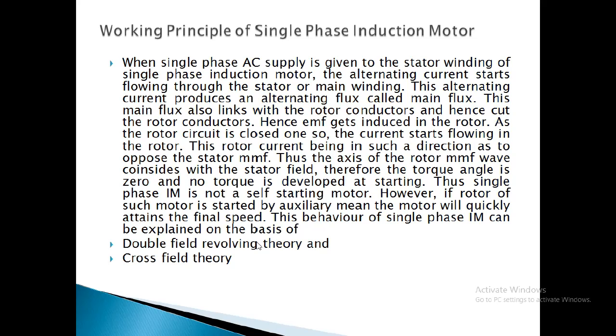if ceiling fans are not run, at that time, due to the discharge of the capacitor or charging down of the capacitor, if you just give a jerk to the fin of a ceiling fan, it starts to rotate. So due to some external force given to the single phase induction motor at the starting, it gains the speed. Okay, and this type of behavior of single phase induction motor is briefly explained by the two theories named the double field revolving theory and cross field theory.